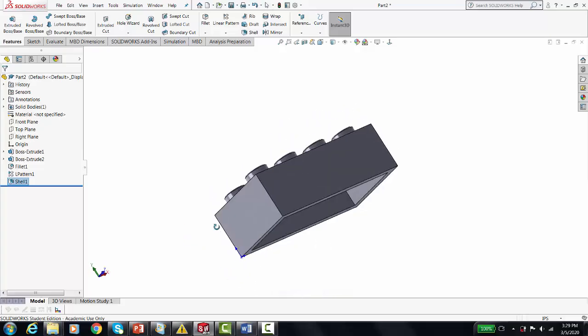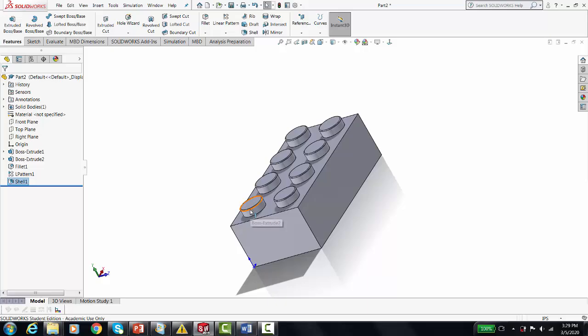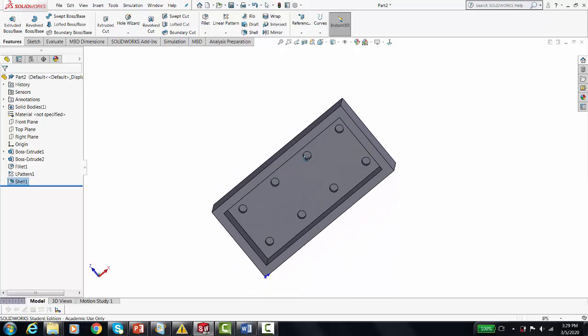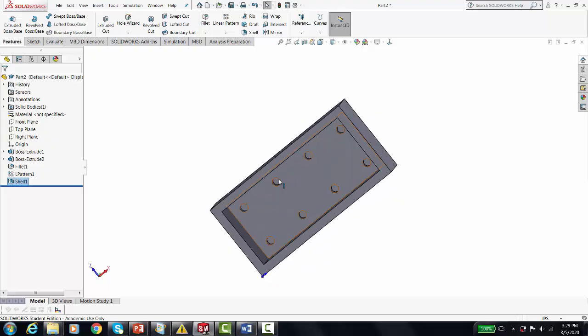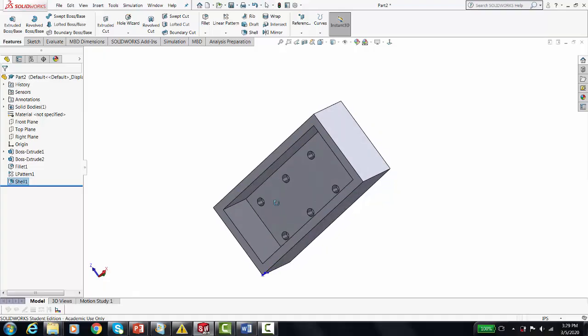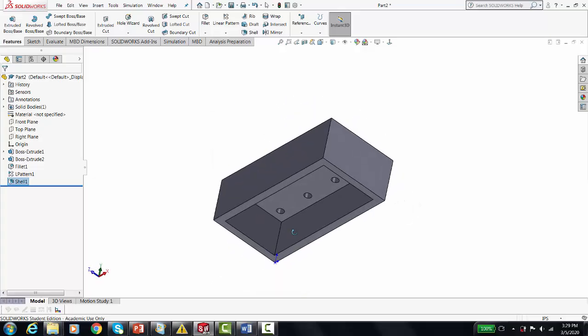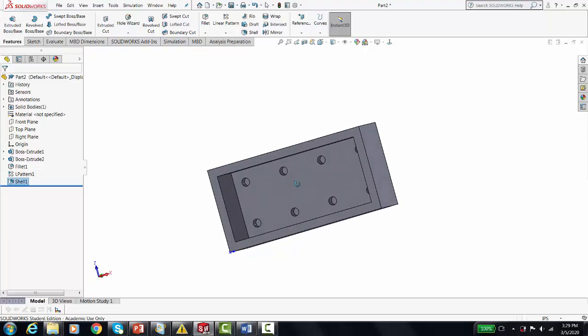Thickness value is greater. Okay, so we'll see how this works. And that worked okay. It was having some problem with these small radiuses on the bottom, but we managed to succeed. And if you actually look at a Lego block, you see it shelled out the bumps. This is kind of why I did the shell second, because if you look at a Lego block, they make these by injection molding, and you will see these little bumps because they have a uniform shell thickness. So there's my Lego block with the shell, and all I need to do is add my tubes on the bottom.